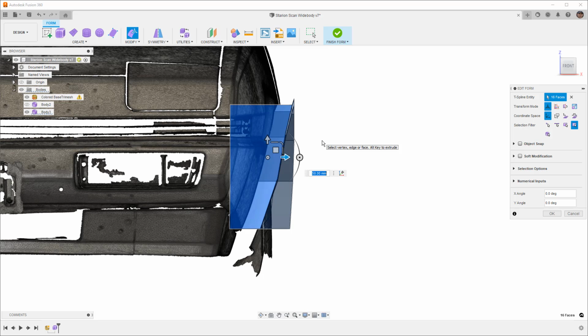And this car right now has a 15-inch rim with a 215 tire. Now, I know for a fact that on these flat side cars, plenty of people have tucked 9-inch wide rims under the fronts of these. You need to do a little bit of work with coilovers to get some more clearance, and you need the right size rim. I've seen 17s, I've seen 18s on here with those 9-inch wide rims.